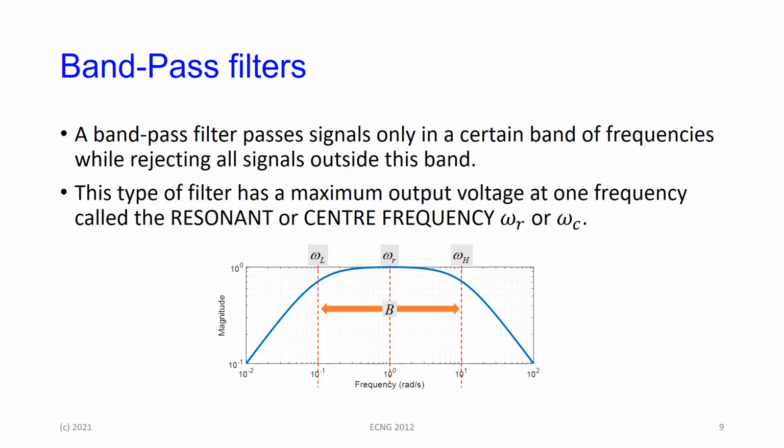Right. So that takes care of the low pass and the high pass filters. And as I said, creating higher order filters now is just a question of cascading second and first order filters as many times as you like. There are ways of designing them with fairly complicated R and C networks, and I'll comment on that at the end when we speak about some final things.